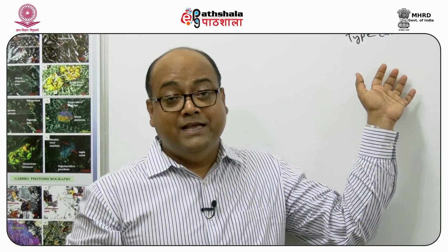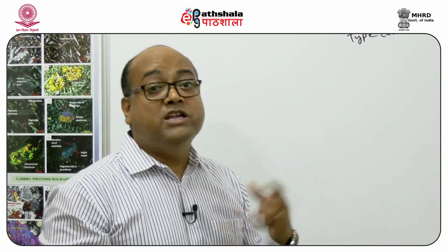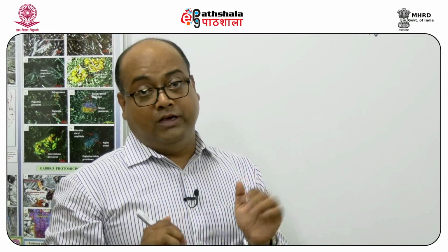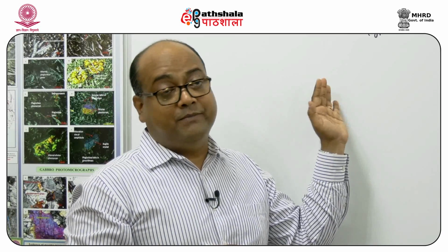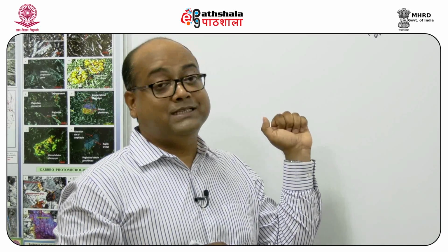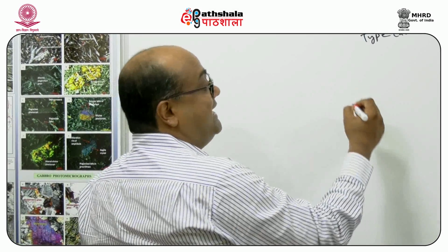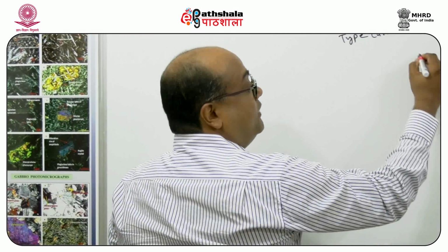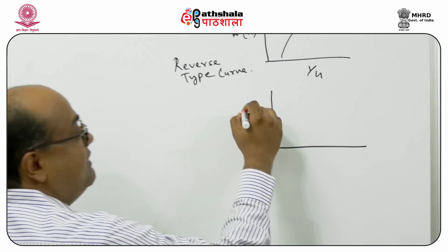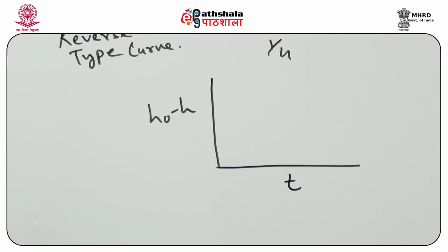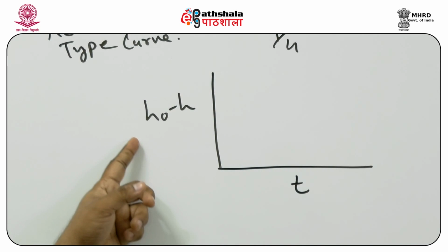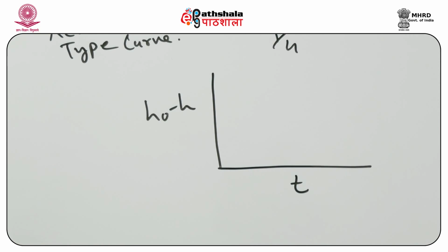Now, how is this curve used in the graphical solution? Remember that what we measure in the field is drawdown only. So for the graphical solution given by Theis, we measure drawdown in the field with time, in a very similar manner: H0 minus H on the y-axis and time on the x-axis. Again, these two variables are plotted on a logarithmic scale.